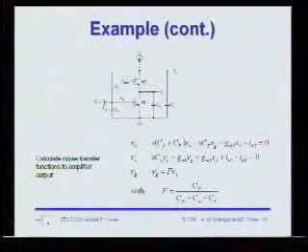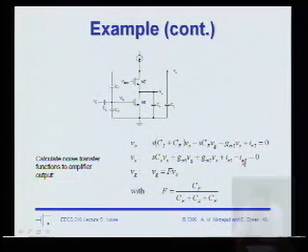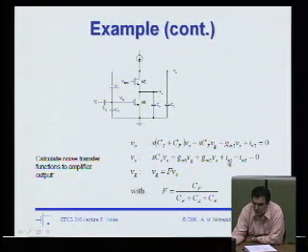In the slides you have a pretty detailed analysis of basically the transfer characteristics from all the noise sources to the output. Again, I'll let you guys go through this in detail and we'll just point out the pertinent results. If you look at this expression, you've got basically the drain noise of the second device, the cascode device. You've got the thermal noise of the first device and the second device here.